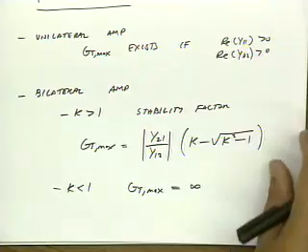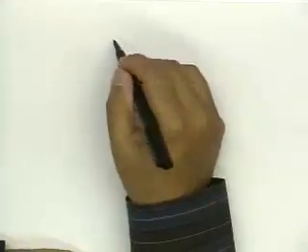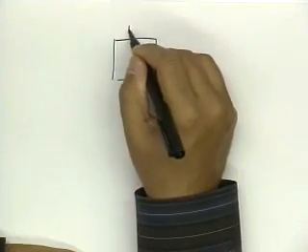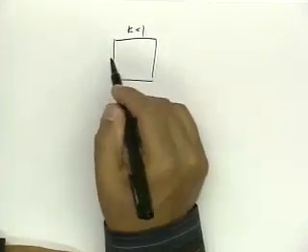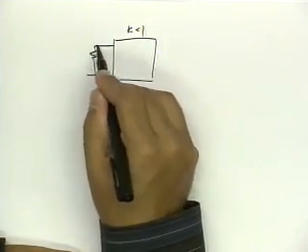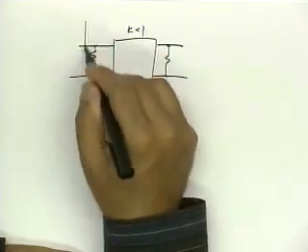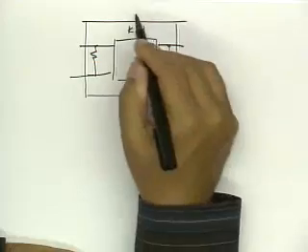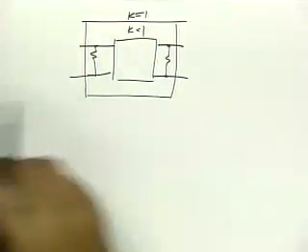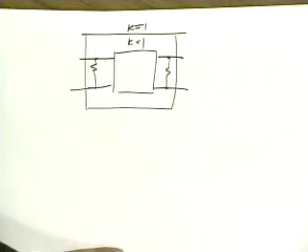And so with the intuition that we just got from the last slide, we can take our two-port, let's say K is less than 1, and add loss to the input and the output, so that we keep adding loss until we hit the boundary, K equals 1.